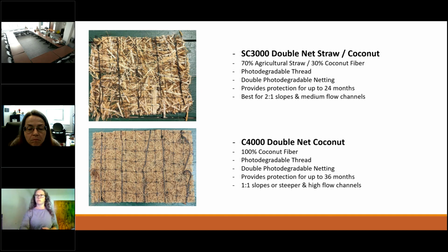Again, photodegradable. You get up to 24 months of protection with that. And for some higher flow situations, you can go in with a 100% coconut fiber type blanket. Again, this gives you a longer lasting protection. So you're looking at up to 3 years of protection on this.